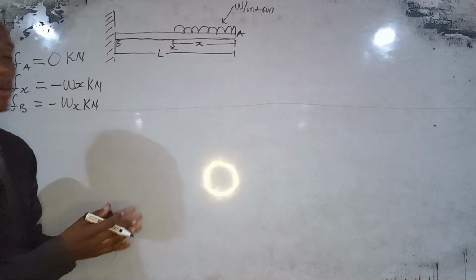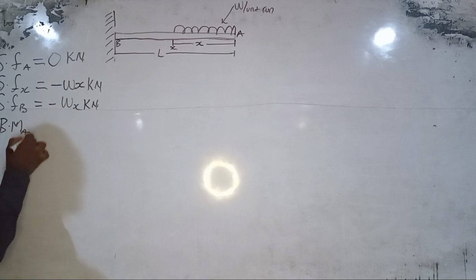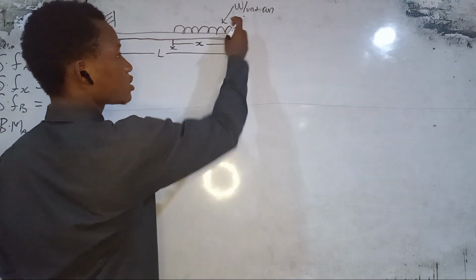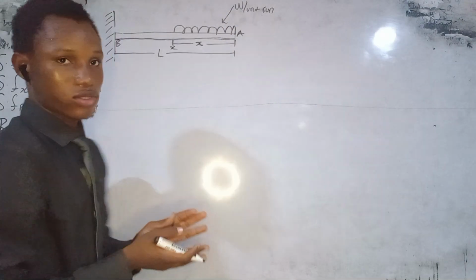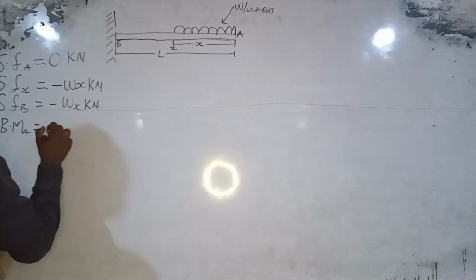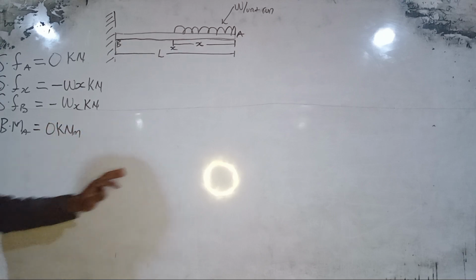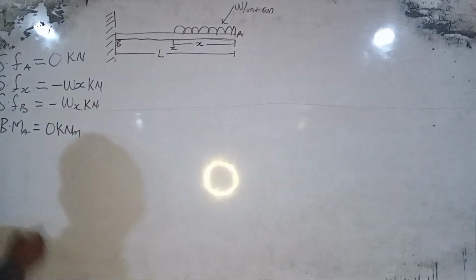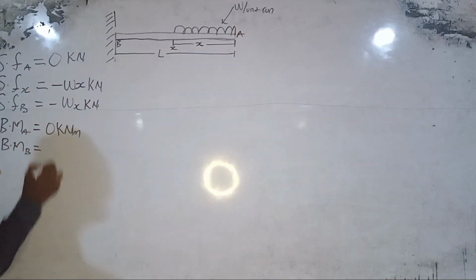Now, if we move on to our bending moments, the bending moment at A, since there is no distance between A and A, W times 0 will still give us 0. So it is equal to 0 kilonewton meter. That is our bending moment at A. But now our bending moment at B will be equal to...